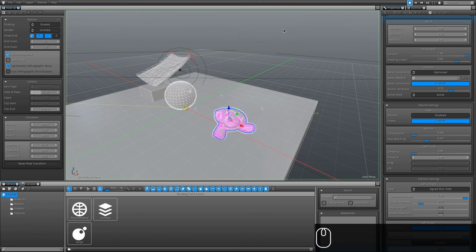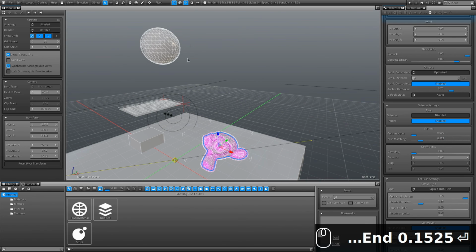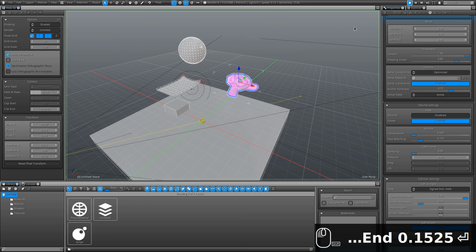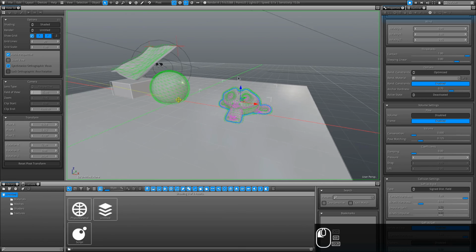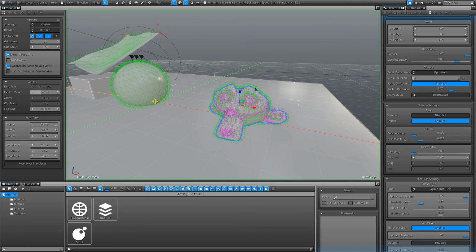And we can see that now there's a lot more absorption on the individual nodes. Let's set something to 0.125 to have something that is comparable to our ball here that we initialized earlier. And if I slightly drag it up and repeat, we're going to see the effect that this has. We can see that now our Suzanne is very elastic and bounces on the floor. I hope that was helpful and gives you a good idea how to set up soft body physics.